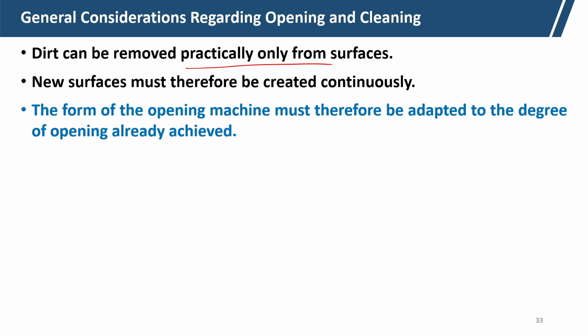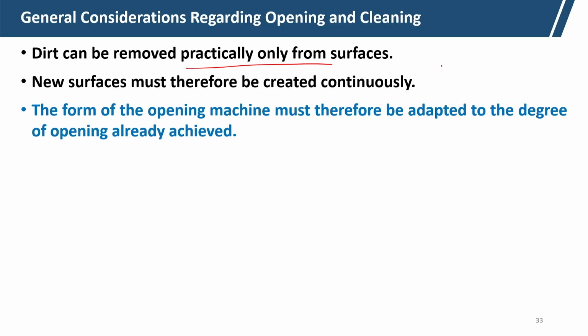Depending on what type of material is coming, we have to change the machine. For example, in the blow room line, the initial machine will do coarser beating, but towards the end we have fine beating, the monocylinder cleaner, where very fine spikes should be there.